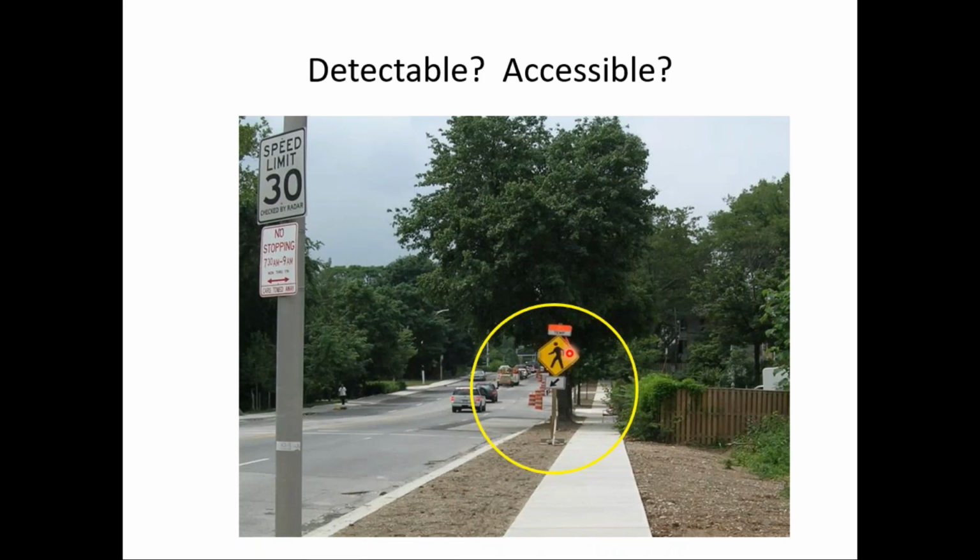Well, remember I talked about subpart E, communications. We have the sign here to alert pedestrians. It looks like what they did was put in a temporary crosswalk in the middle of the block here. And so pedestrians were to cross the street here and then use the other side of the street for maybe a block or two until they could go back to the original side of the street. The problem with this sign, that's a standard sign from the MUTCD, but the problem with that is that it does not communicate with the visually impaired. A blind pedestrian cannot see that sign.